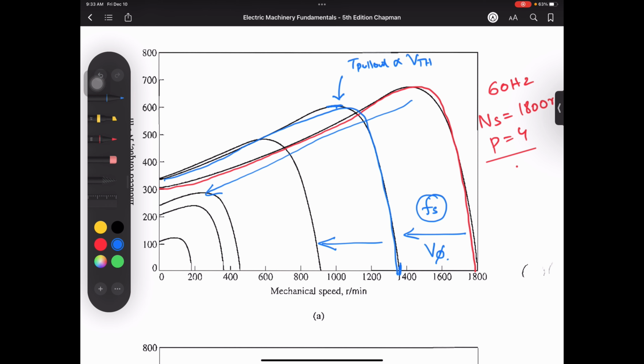Supposedly, the mechanical engineer has told you that you require a torque of approximately 10 Newton meter. Now for 10 Newton meter, he must tell you the speed at which that torque is required. This is very important. Because maybe if you are in the cotton industry, yes, you require a constant speed. There is no issue on that one. But when you are in the glass industry, or maybe the steel industry, your speed changes. And when that speed changes, your torque has to be equal to that, even at that speed.